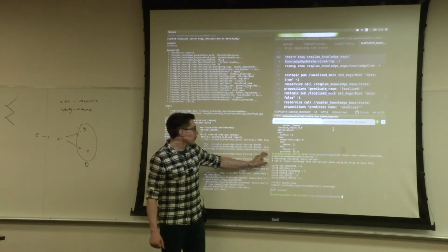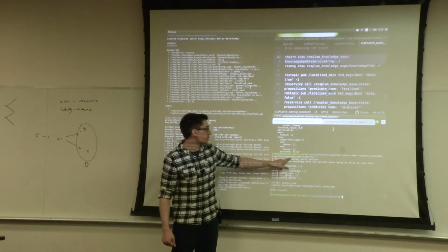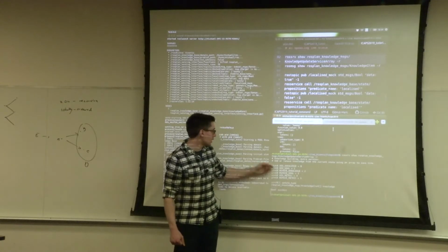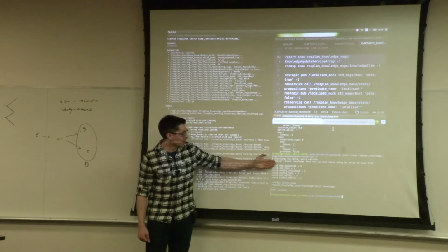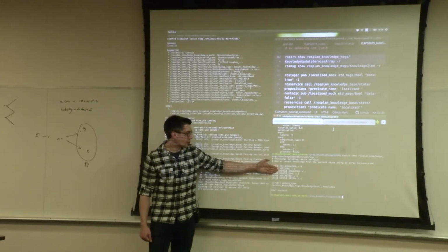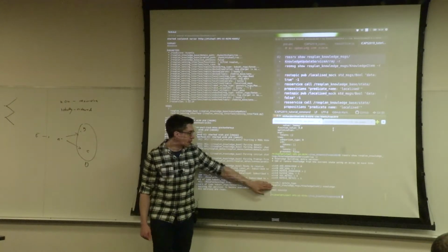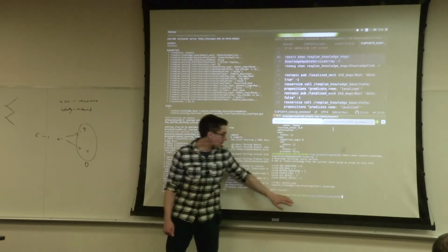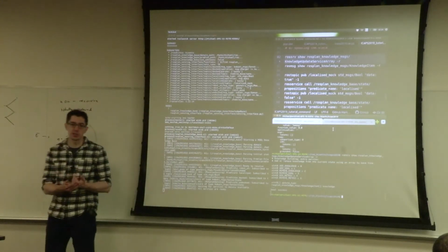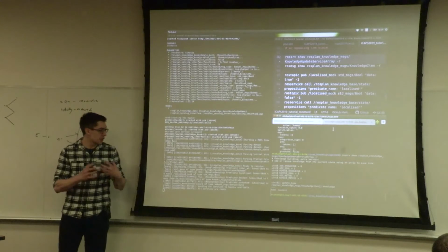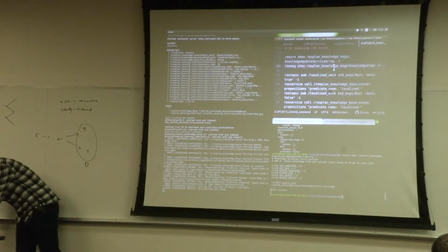So when we call this service, with ROS knowledge update service, you call with an update type. Either we're adding knowledge or we're adding a goal, we're removing knowledge, we're removing a goal, we're adding a metric or we're removing a metric, and then an array of knowledge items. And each knowledge item represents a part of the state. It could be propositions, functions, objects, instances, a number of different things. And I'll show you what the knowledge item looks like.